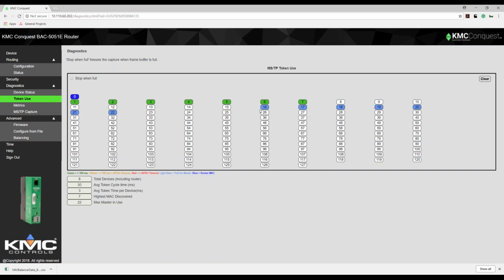Very good. So we're almost out of time, but we're going to take about 1 or 2 more questions here. So going back to the unstable bus status, what will actually cause that? Will a device powered off cause that? Generally, if a device is powered off, assuming it's wired properly, a device powered off would not cause an unstable status. I would say more commonly if a device is offline, or offline because it's unpowered, there's probably some other wiring issue or power related issue that we want to tackle.